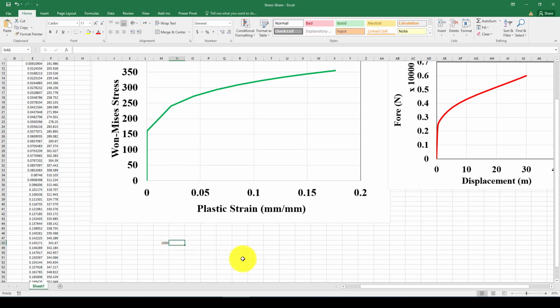So the area is about 800 times 10. Now this is the area and this is the force. So it is equal to 8000. Now here is the pressure we want to apply on that edge or that surface. Now it's equal to the force divided by this area. So now the amount of pressure is 0.125.